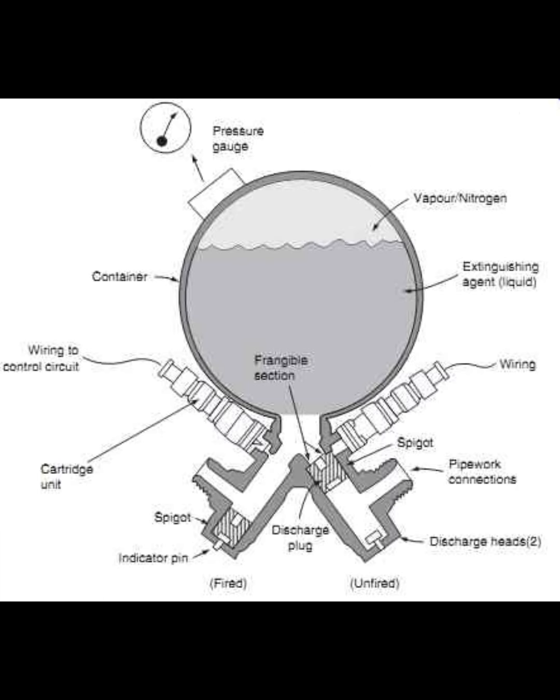What method is used to release the fire extinguishing agent in a typical turbine engine fire protection system? Electrically discharged cartridges. Explosive cartridge squibs break discs and plug. What method is used to determine proper fire extinguisher container pressure? Container gauge.